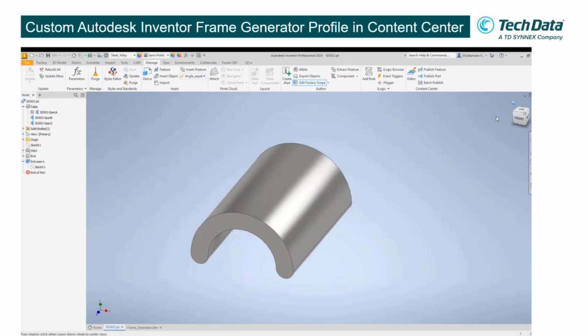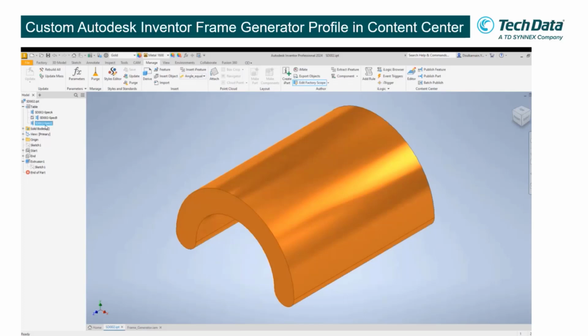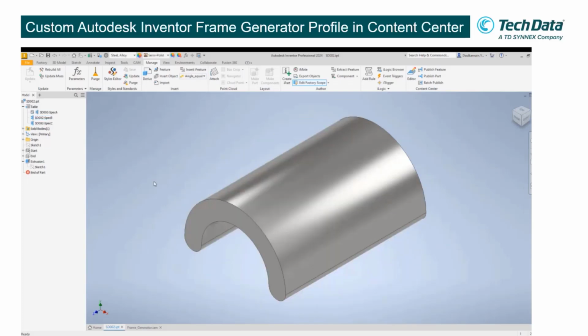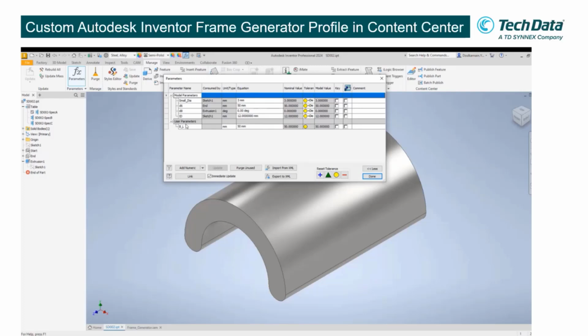So next we just need to alter this, or in other words, to save this into the Content Center libraries. So how do we do this? I first make sure that we have parameters. So user parameters for length, I usually use b_l equals base length, and just for the equation, I can put any numbers first.